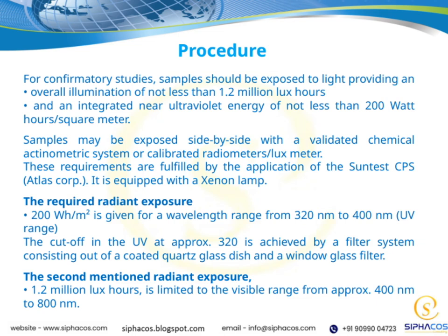tests. Now, regarding the specific radiant exposures, the 200 Wh/m² is targeted within the wavelength range of 320 to 400 nanometers, which falls within the UV spectrum. To achieve this cutoff at around 320 nanometers, a filter system is used, consisting of coated quartz glass and a window glass filter. This setup filters out wavelengths below 320 nm, ensuring that only the desired UV range reaches the